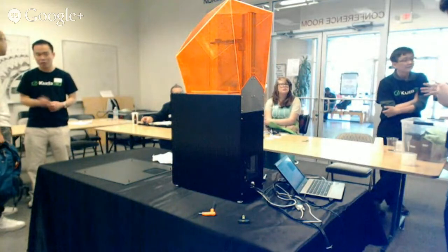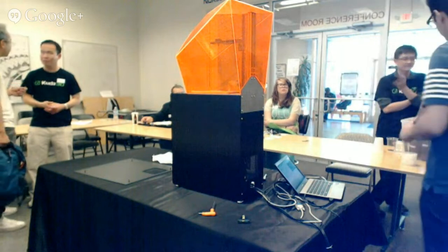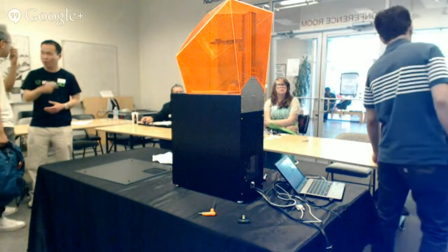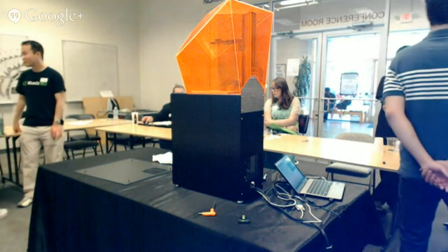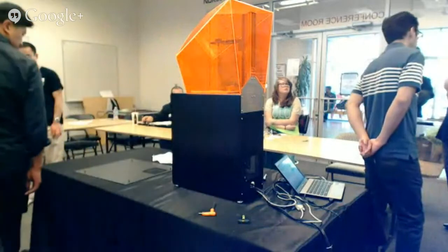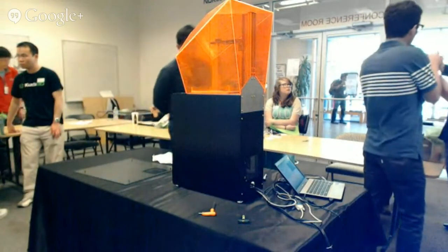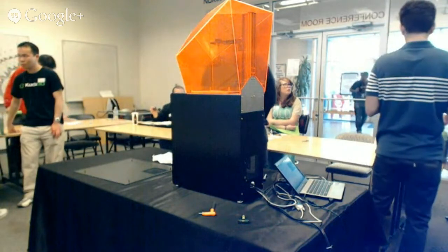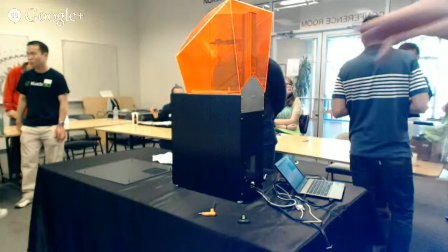That doesn't mean that you have dimensional resolution of 35 microns. You've got 36 or 37 microns. You have 37 micron feature resolution, meaning if I have a 37 micron feature, it will appear in the print, but it won't necessarily be 37 microns tall. More than likely, we're talking about a particle floating in the air between your lensing, and all kinds of stuff can happen.